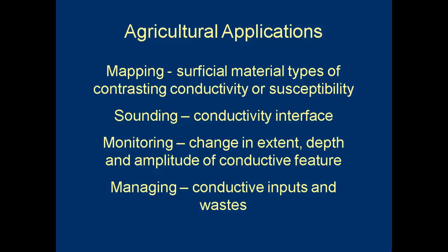Following theoretical development in the 1960s, we have developed instrumentation and techniques for sounding conductivity to several distinct depths. The robust interpretability of these soundings, where the Earth has conductive layering, allows the estimation of layer conductivity and the depth to layer interfaces.